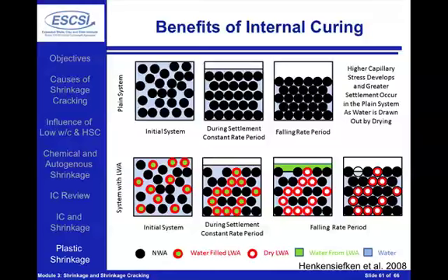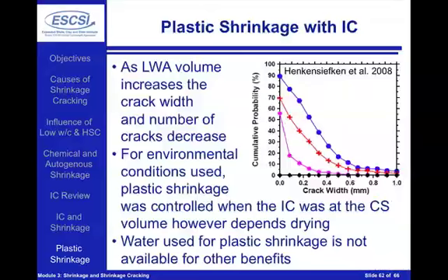On the bottom, we see a system where internal curing is used, shown as a water-filled lightweight aggregate as the red dot with the green center, which is the water from the lightweight aggregate. And as the system consolidates, water can come out of the lightweight aggregate, relieving this pressure and essentially providing more water that's available inside of the system. Until you started to evaporate, or until you started to pull all the water out of the lightweight aggregate, you don't really reach that falling rate period where the stresses would be high and would start to cause the potential for cracking. So the whole idea here is you could use that water at very early ages.